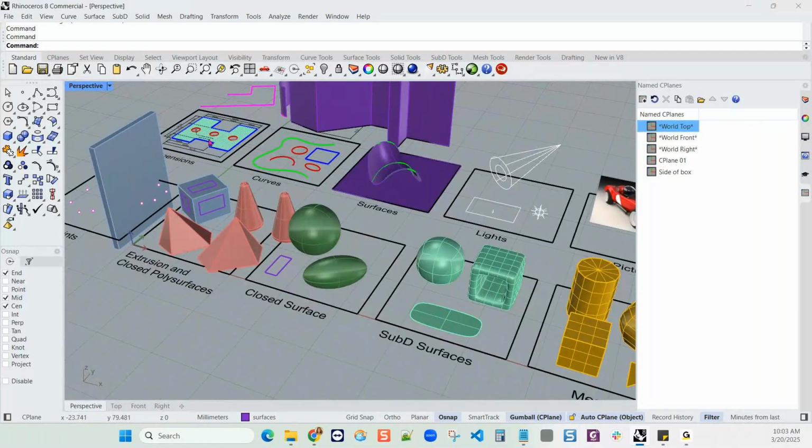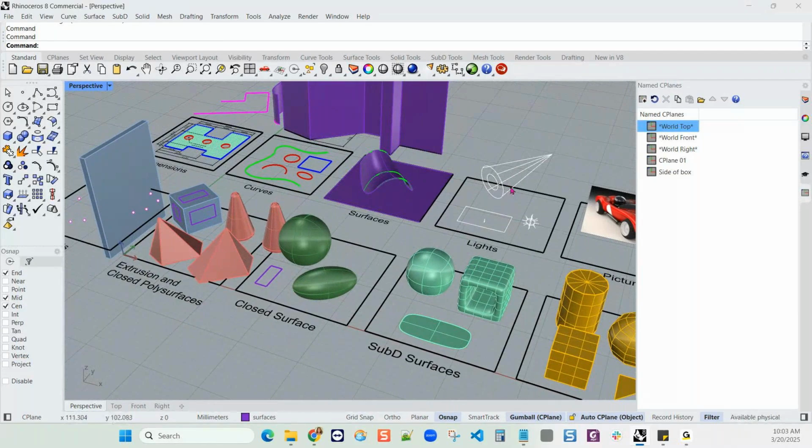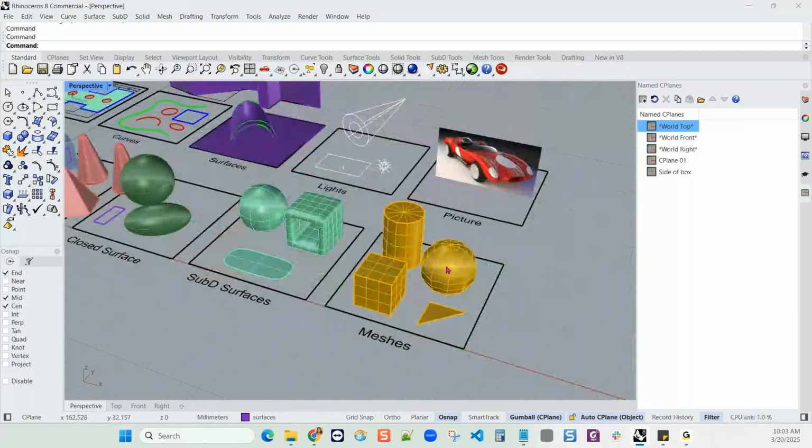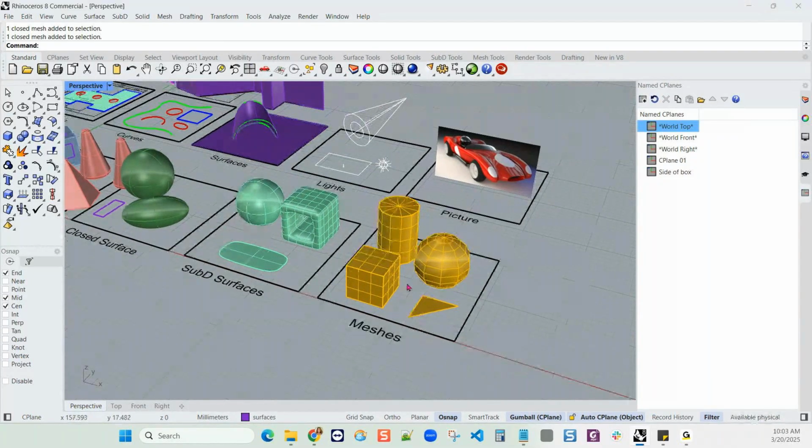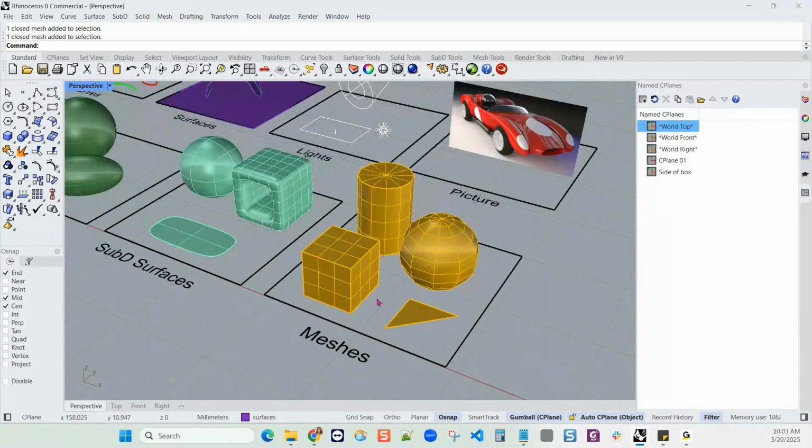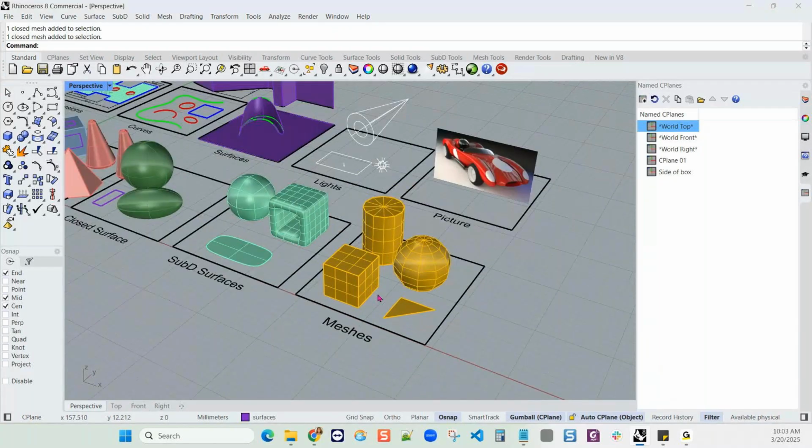I think those are the main things I need you to know. Rhino does create meshes, but we've brought meshes in from a SKP file, a SketchUp file. Some are DWG and DXF. Also, OBJ is a mesh. Most formats are mesh. The formats for surfaces are IGES and STEP. So if you're going to SolidWorks or even to AutoCAD that supports NURBS now, you want to use IGES.